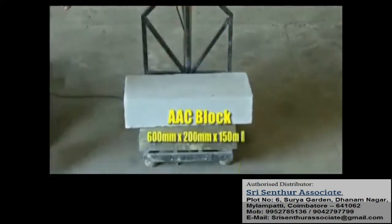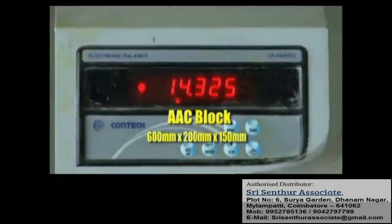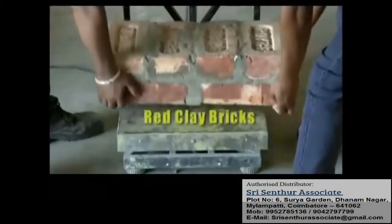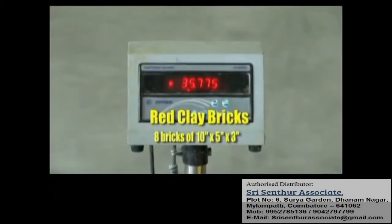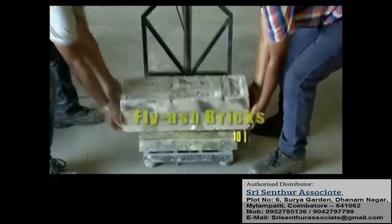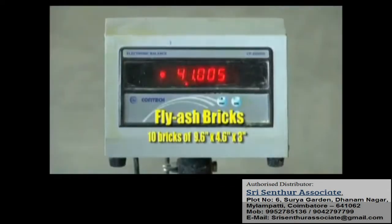The weight of one single block is about 14 kgs, whereas 8 red clay bricks, equivalent of the same volume as the block, weigh 36 kgs, that is, more than double. The 10 fly ash bricks of the equivalent volume are heavier, at about 41 kgs.